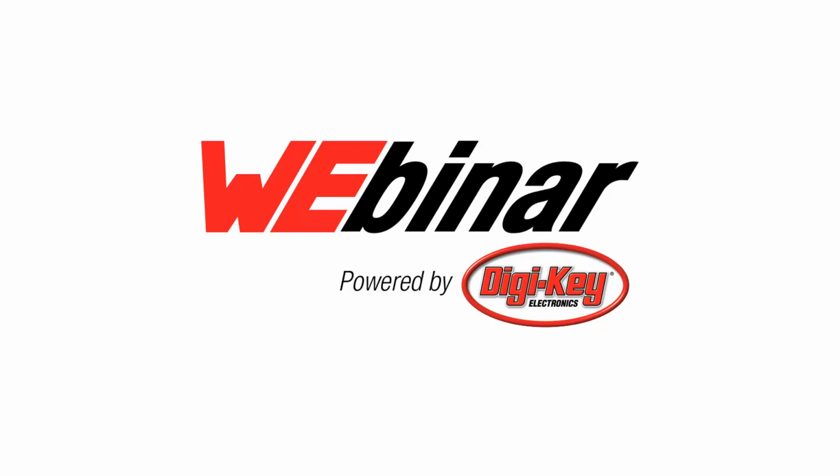Sure. So, like I said, pollution degree 2 is what we typically design to meet here at Wurth. That's anything like I said, a laptop charger, your household appliances, your standard office type environment, if you will. The majority of the pollution degree 3 type of designs that we see here at Wurth are, let's say, an industrial application where there could be a lot of dust or contaminants or that type of stuff within that environment.